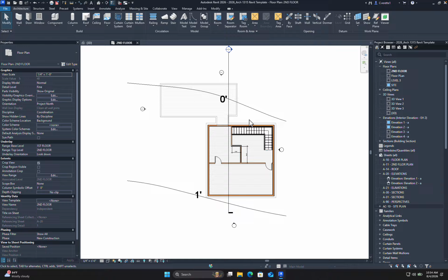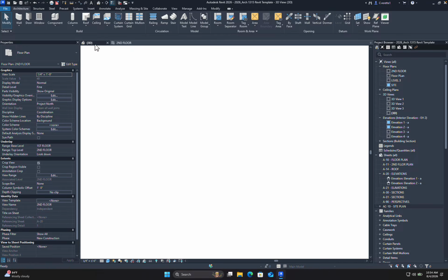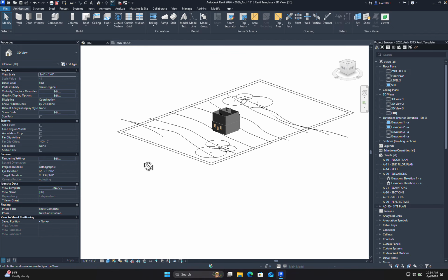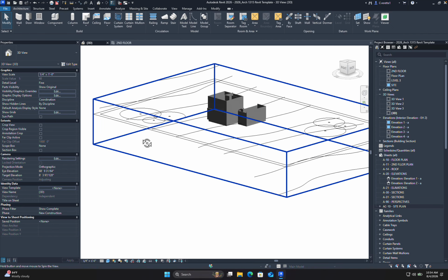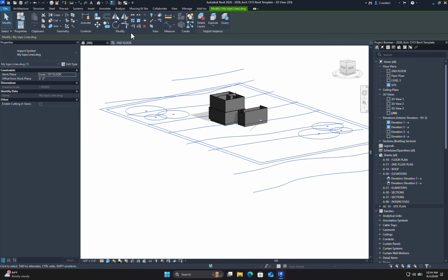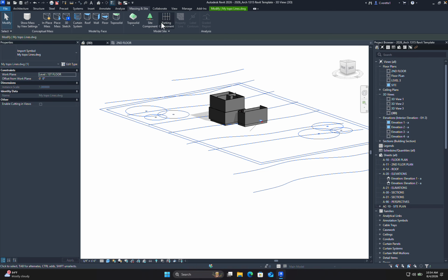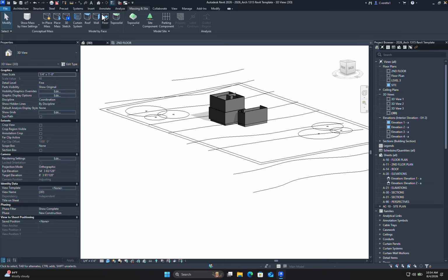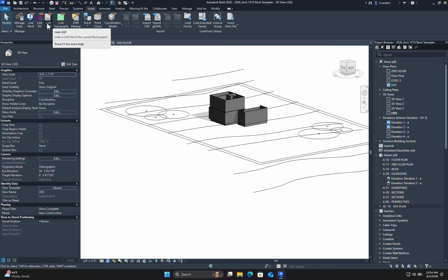What is the topography you gave us in 2D? Yes, that was a great question. Gavin just asked, is the topography you gave us in 2D? It is. Maybe we'll end with that because it's just so terribly easy. You can take DWG drawings, go to Massing and Site, then Toposurface, and we'll create from import, right? That's an import that I put in there. If you want to know how to import it, we'll go to Insert, and we can insert a CAD file. That's basically what I did.